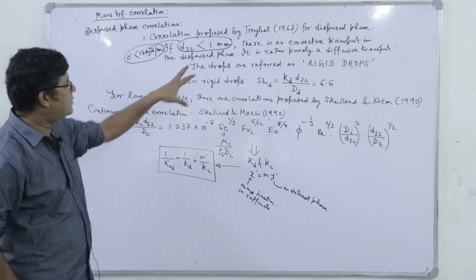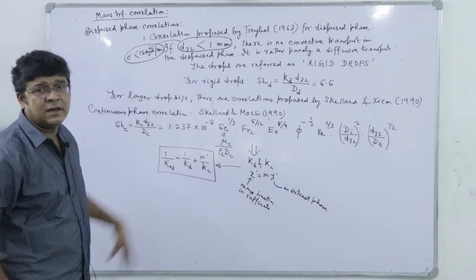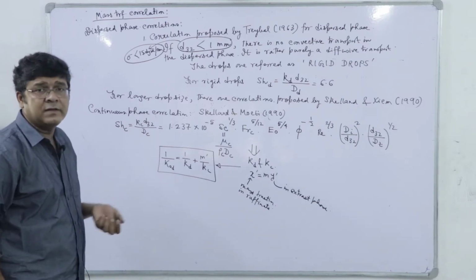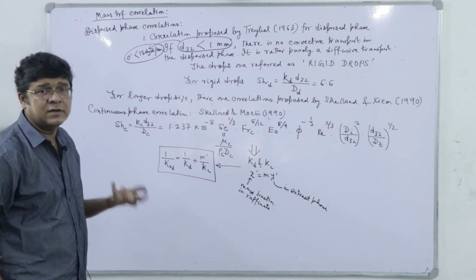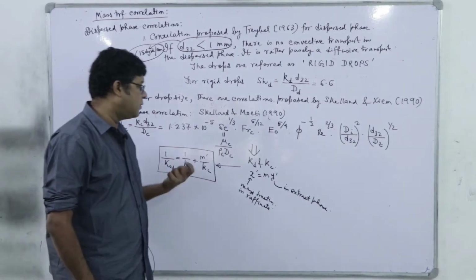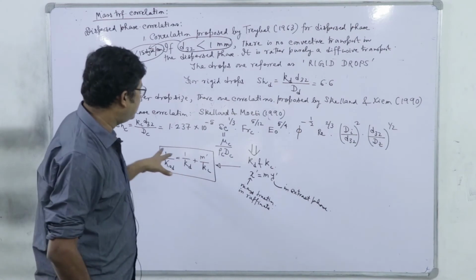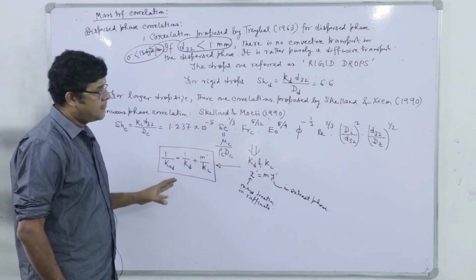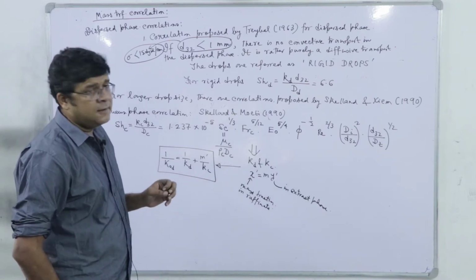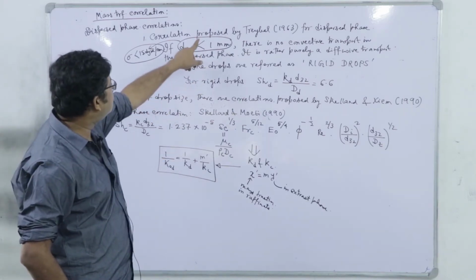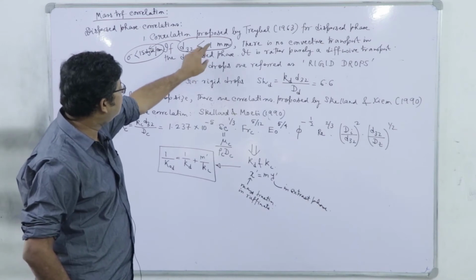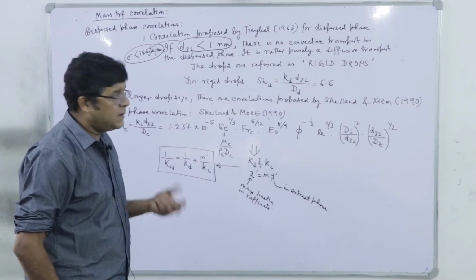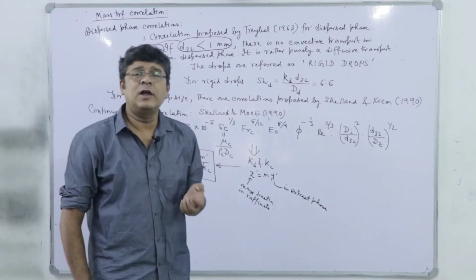From these mass transfer coefficients, we can write down the steady state material balance, and we can go for calculations of the transients, how the concentration in a mixer settler is changing with time. That is a different issue altogether, and we are not going into that discussion right now. So next, what I have mentioned here is a dispersed phase and a kind of drop which is called a rigid drop. In a rigid drop, diffusive transport is the only transport.